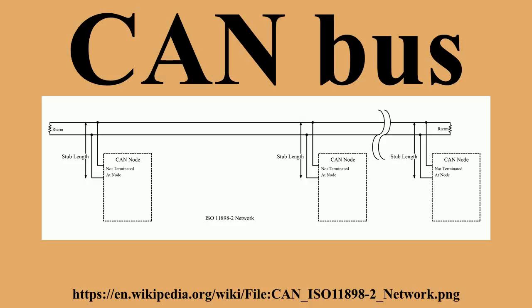The distinction between CAN base frame format and CAN extended frame format is made by using the Id bit, which is transmitted as dominant in case of an 11-bit frame, and transmitted as recessive in case of a 29-bit frame.